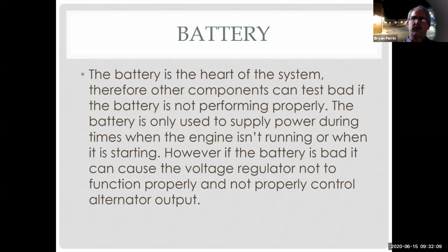If I rush through and go, yeah, I know it's not good, but I really think I just have a bad alternator or starter, they have a high likelihood of testing bad with a battery that's not functioning properly, but yet when you replace them, you still haven't solved the problem.